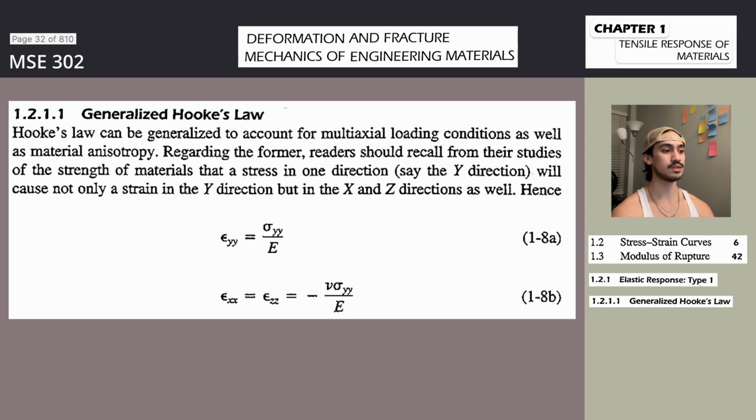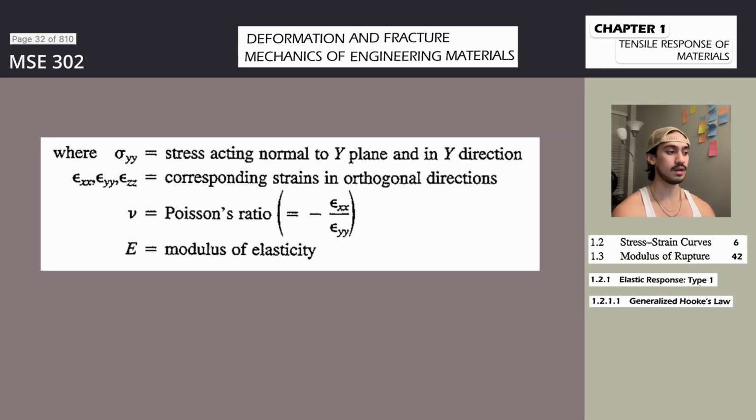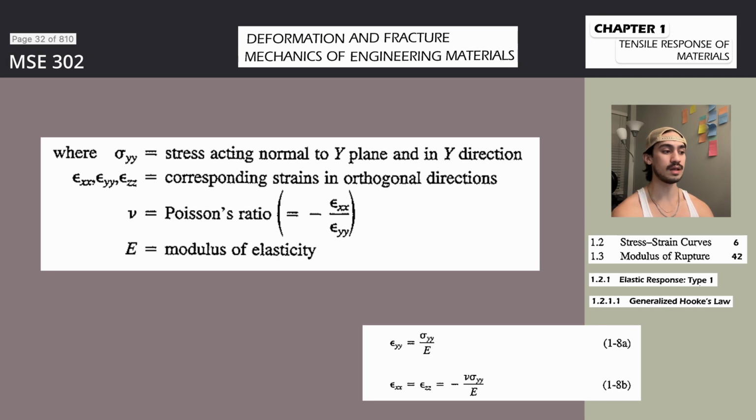That the curve continues to rise to a maximum stress level reflects the increasing resistance on the part of the material to further plastic deformation, a process known as strain hardening. The portion of the true stress-strain curve from the onset of yielding to the maximum load may be described empirically by the relationship generally attributed to Hollomon.